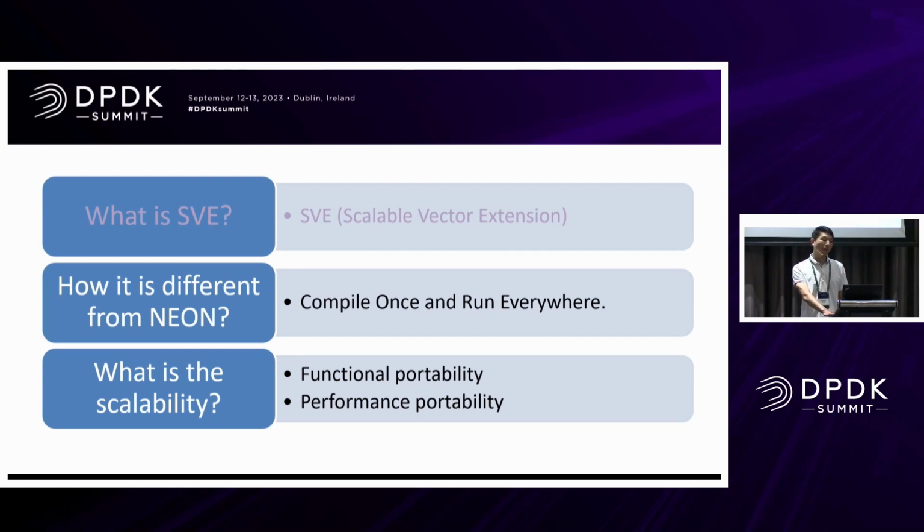We just talked about SVE and what's the difference from the traditional vector. In the traditional case, the vector length could be fixed. For example, on the Arm platform, the Neon extension is 128 in bit width. And in some other architectures and in more advanced generations, the vector bit width can be wider, to 256 or 512.